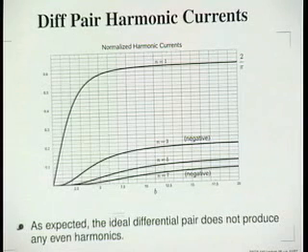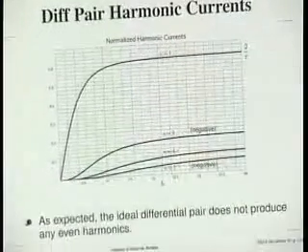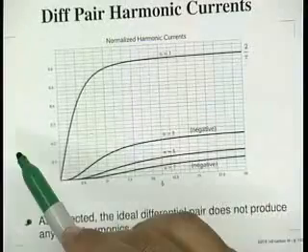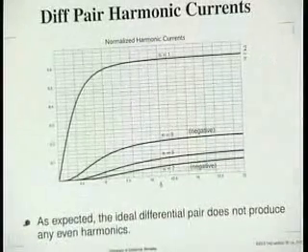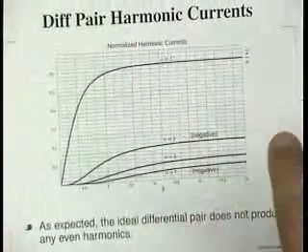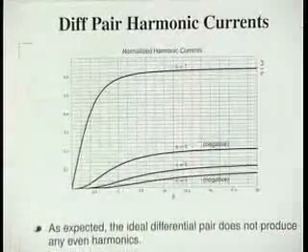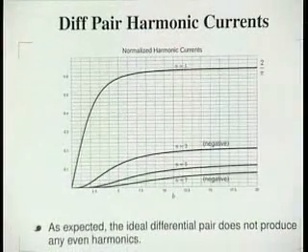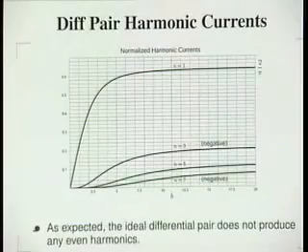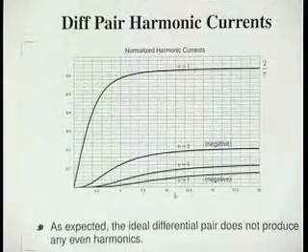Now here we can see that the bias current naturally limits, right? That's because this waveform here naturally limits. And the reason is there's only current IEE. IC1 can never get bigger than IEE, right? So there's a natural limiting mechanism. In the bipolar amplifier, the limiting mechanism is due to the fact that we somehow force the bias current to be constant. If we don't force the bias currents to be constant, then you'd find that the current just increases without bound. Okay?